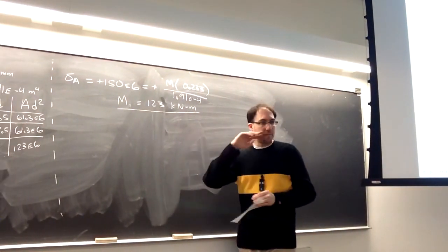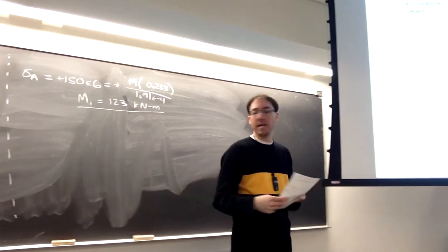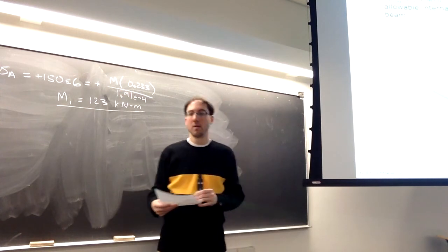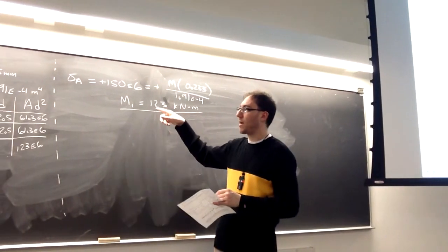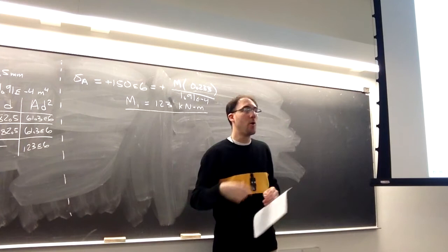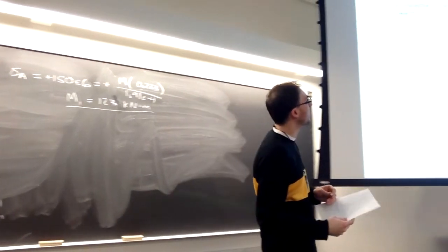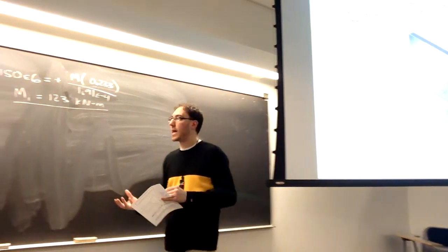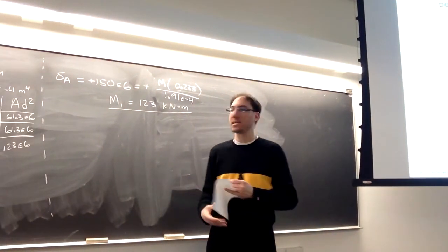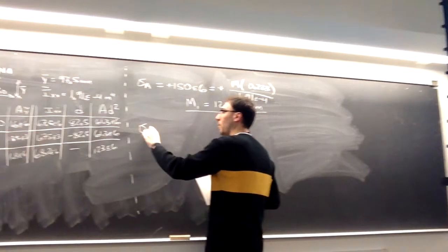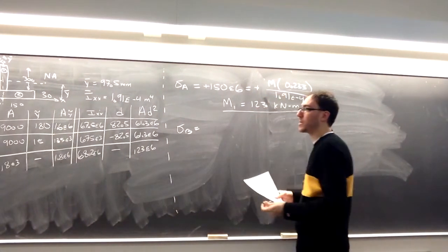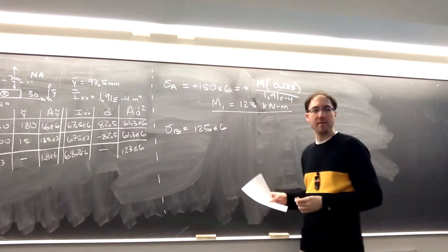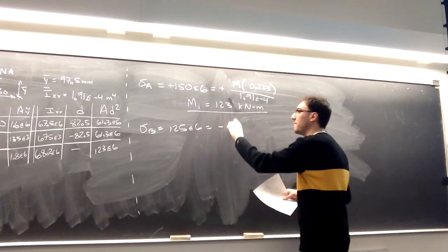And what else do we have to check then to see is this our answer for M or not? Check at B, right, because we're not only looking at the compressive stress exceeding 150, we don't want the tensile stress to exceed 125. So B, because it's at the bottom, we're going to say is the place where we have the most tensile stress. So we also don't want that exceeded. So if we set B equal to the allowable maximum 125, will be negative.